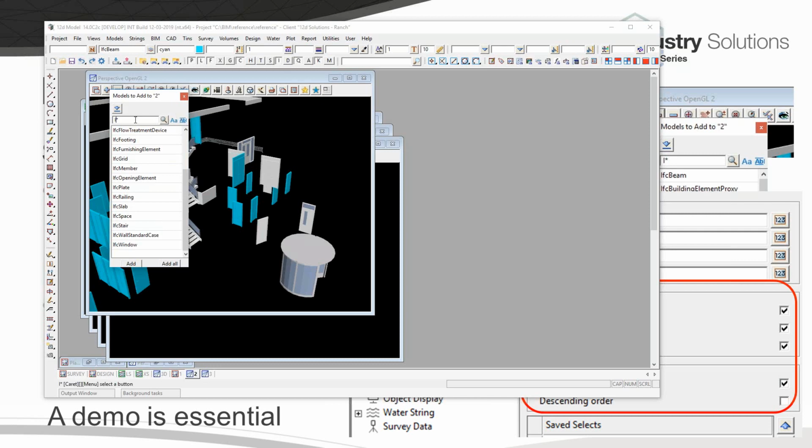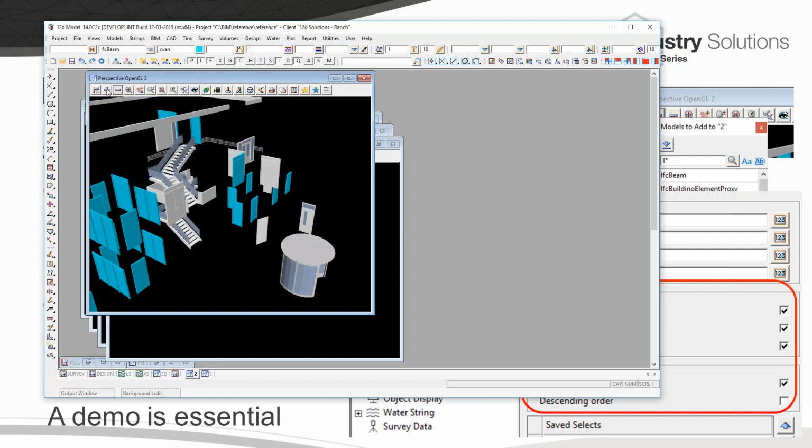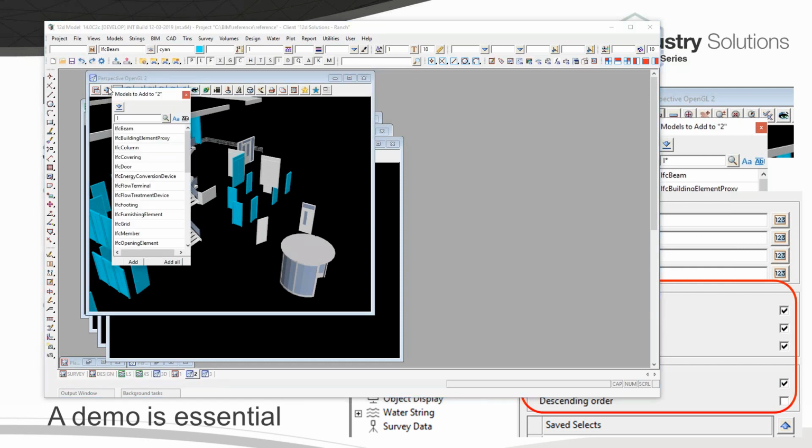Now, the other interesting thing you can do here, because it's now in the search, which didn't exist before, is you could start typing more letters. Before you typed one, but it puts your cursor right in there, so you can continue typing more letters. So it gives you that extra functionality as well. Now, what happens if I don't have whole word turned on? When I had whole word on, it puts I star. Well, if you don't have whole word turned on, and I then type I across there again, it doesn't bother putting the star, because it's then just searching for an I anywhere in anything. So again, you've got all that extra functionality. You can just use it as you did before, or you can get all this extra functionality.